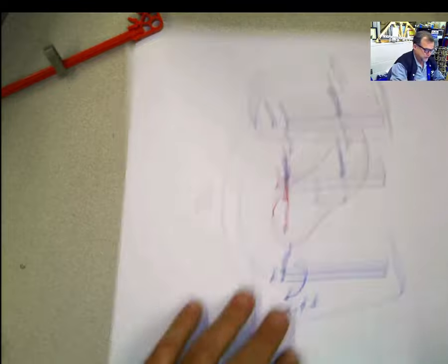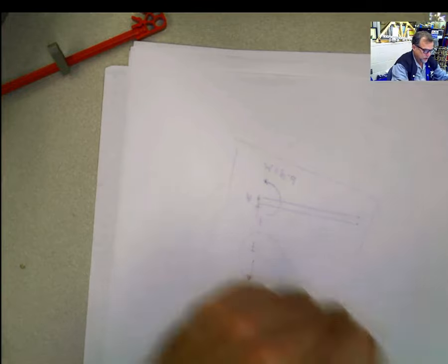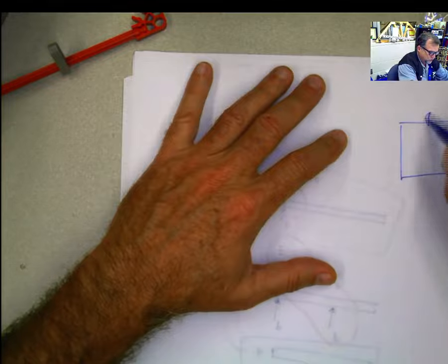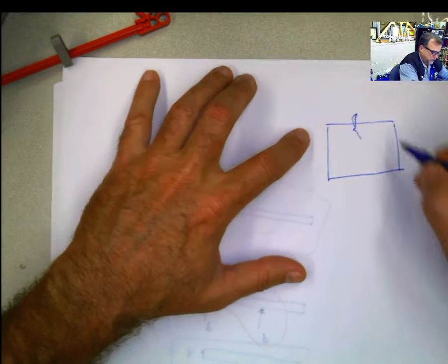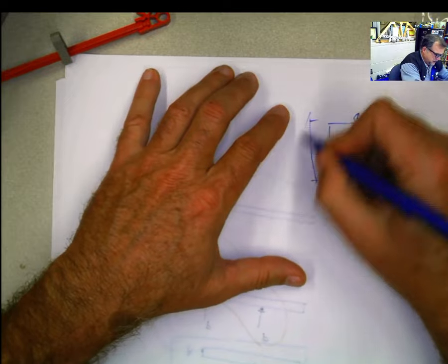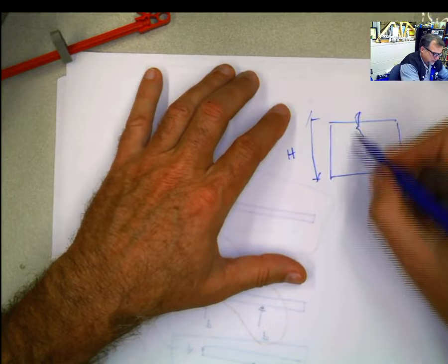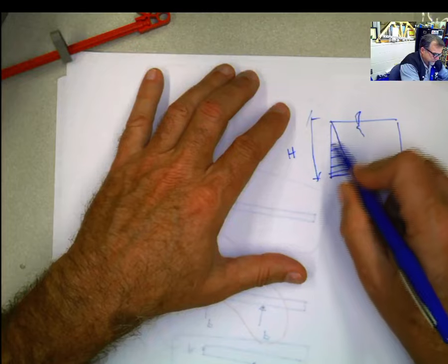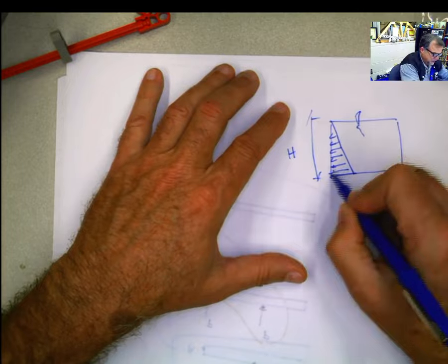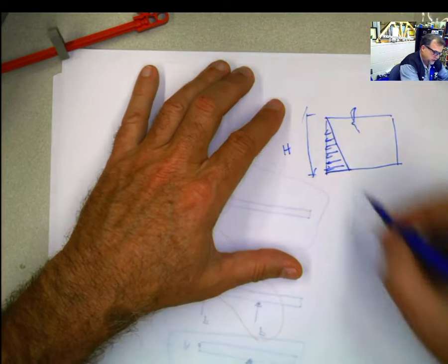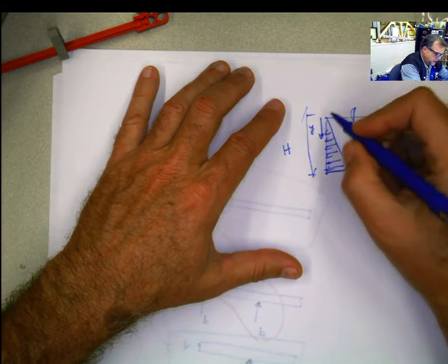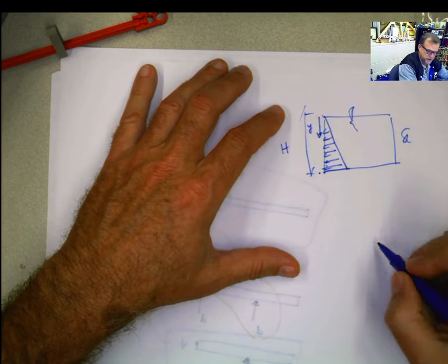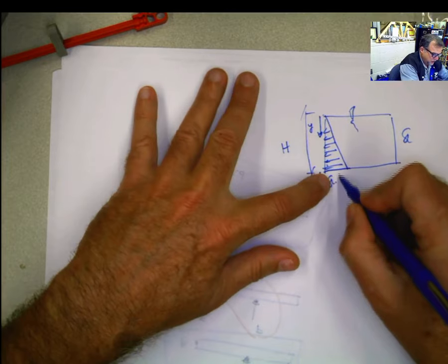Remember, if this is a fish tank, a pool or something, and this is the level of the water, and this is h, the total height of the water. So basically the pressure over the walls here, this pressure is going to be like that. The force is going to be this triangular distributed load. If you call this distance y, as you're coming down from 0 to h basically, and the unit weight of the liquid is gamma, the pressure here is going to be gamma h,